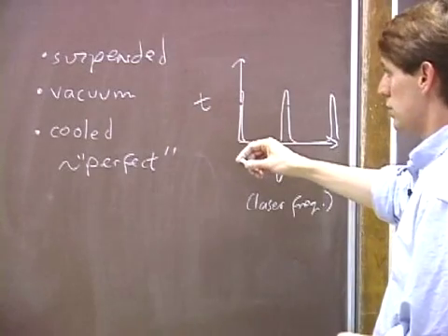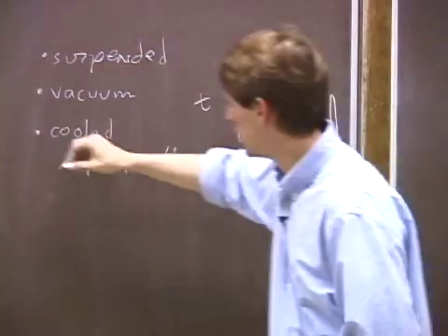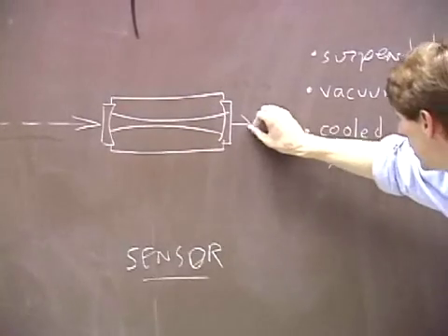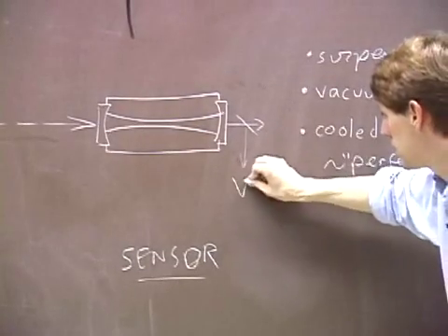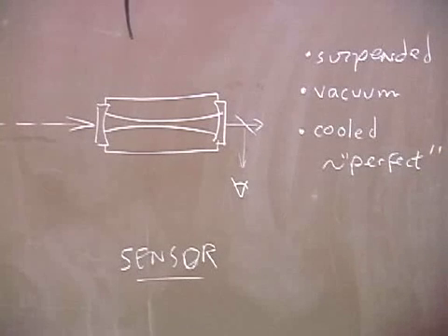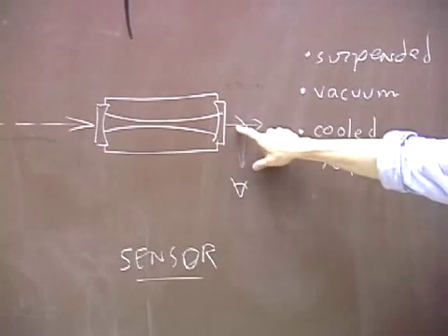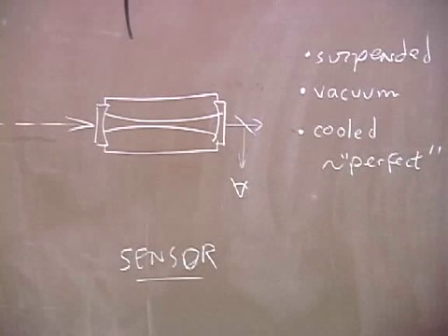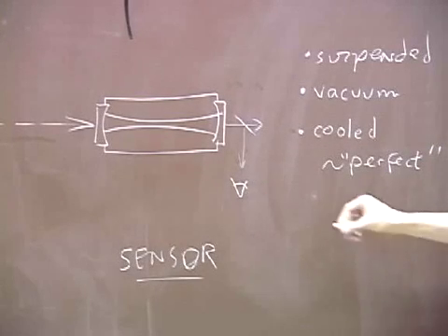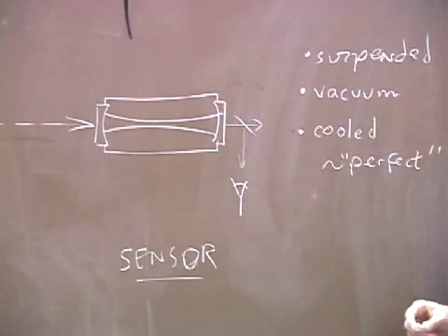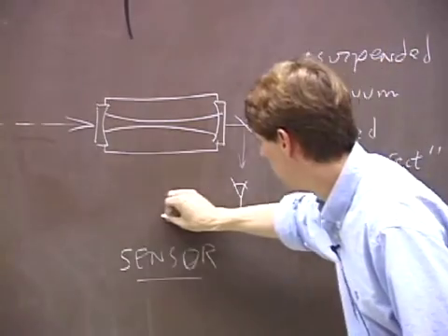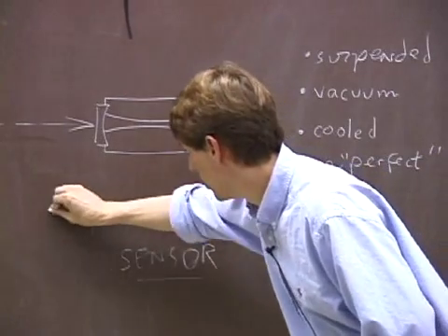So what we might do is take a small beam splitter, put it on the output of the cavity, and tap a small amount of the light and send it into a photodetector. A small amount of the light because we want the rest of the light to use for interferometry, otherwise we wouldn't be stabilizing the system. And we might take the output of this sensor, the photodetector, and run it through an amplifier.